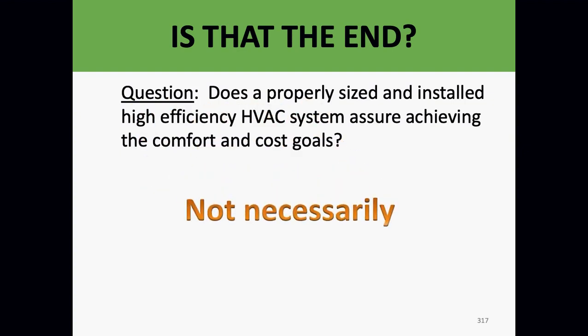Just because it's a properly sized and installed high-efficiency system does not mean it's necessarily going to meet the comfort and cost goal. A building, like a car, is a system. The heat loss evaluation is looking at the system. In other words, "if it fits" is not a good measurement of will it work.